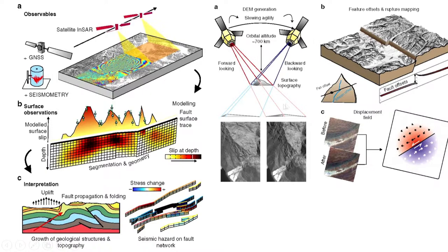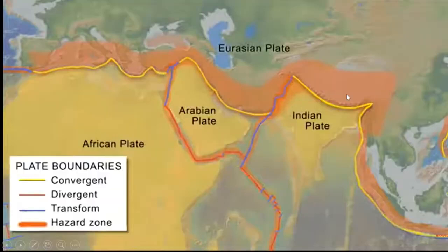Then with the help of this, you can demarcate geomorphic indices. For this you have to have very accurate before and after optical data of high spatial resolution. Once you have it, you can get the ortho-rectified digital elevation model, and once you collect this data, you can do the geomorphic indices study: how much area is active, where, what is the nature, and what is the direction. All this you can demarcate with the help of your digital elevation model data.